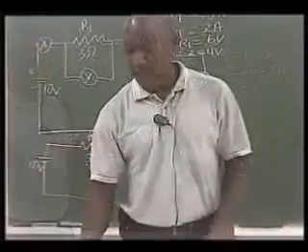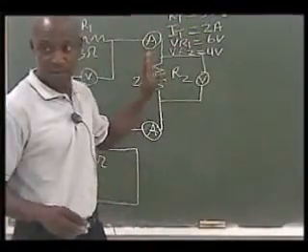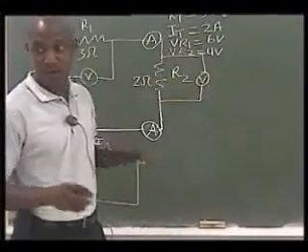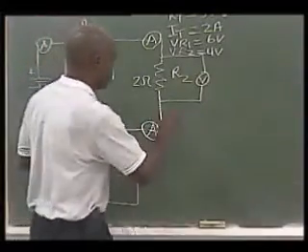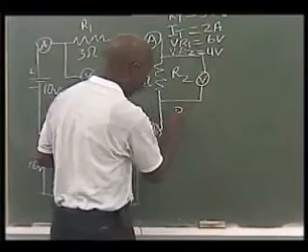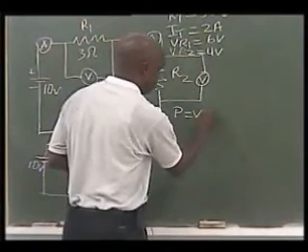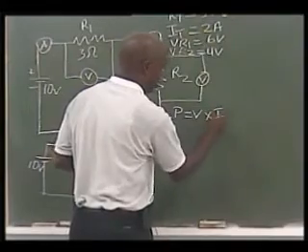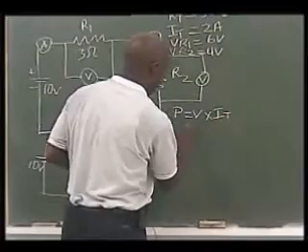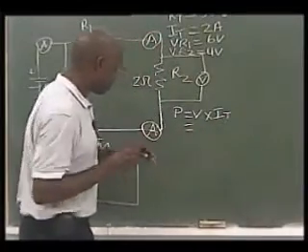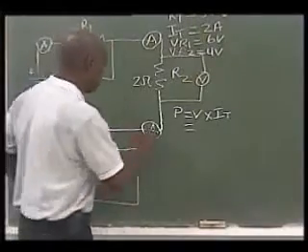Once again, to find the power across the resistors, to find out how much power the resistors are consuming, we use a very simple formula. Okay? It simply says P for power is equal to V, which is the voltage, times the current. And in our case, that current will be IT. Okay? So let's look at the power that R1 is consuming.